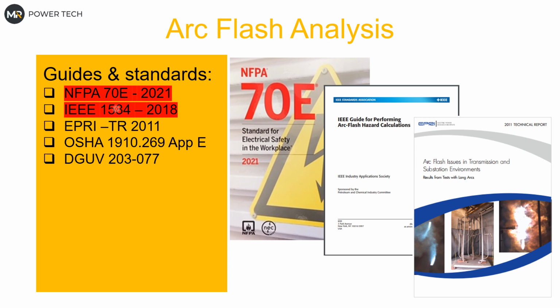230 volts. Because at this level, at this short circuit current, we can sustain arcs. So once they are initiated, they can stay there for a longer time. And below this value, usually they will disappear very, very fast, so there is no associated risk with it. But it's hard for customers to specify something like this. So in a practical, historical way, we usually go down to 63 amp protection level, circuit breaker level. And if there is a need for something more, then we'll go deeper.